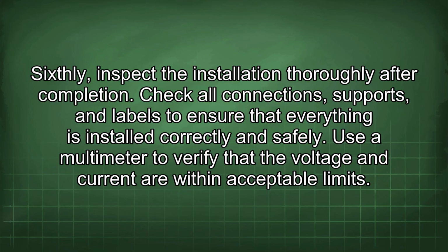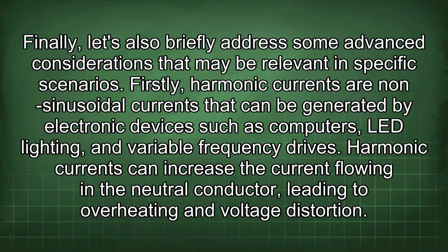Sixthly, inspect the installation thoroughly after completion. Check all connections, supports, and labels to ensure that everything is installed correctly and safely. Use a multimeter to verify that the voltage and current are within acceptable limits. Finally, let's also briefly address some advanced considerations that may be relevant in specific scenarios.